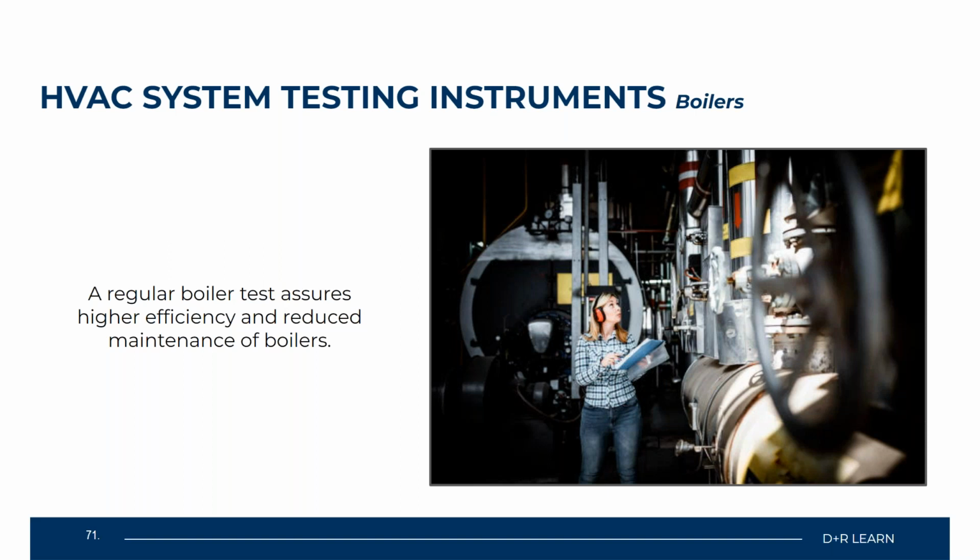We also send supply and return temperatures of the air handler unit during heating applications to the BAS. So not only are we sending the water temperatures to our BAS for logging and reading by the master controller, but we're also sending the supply and return temperatures of our air handler system during the heating application to the BAS as well.